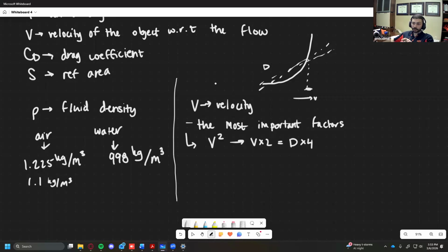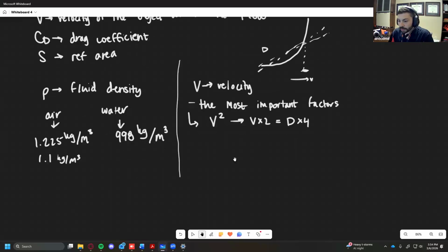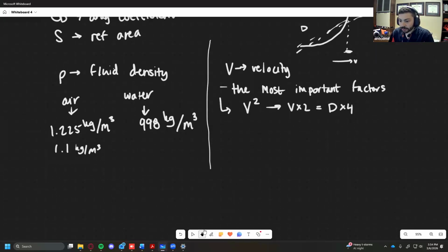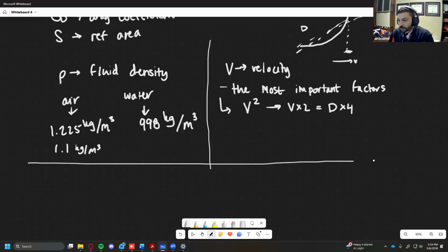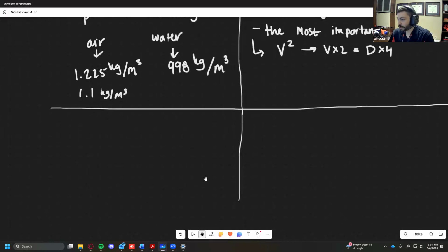This is why, let's file all the way back full circle, weight does not necessarily influence the glide time, but it does induce the speed. You can overcome some of your glide issues by going faster, but you have to be very streamlined, right? So you have to do a better job as a designer making your drag less so that you can fly faster. That's one of the tricky parts here. That's one of the reasons why aerodynamic drag increases dramatically once you get to these higher speeds. So the faster your glider goes, the more streamlined you need to make your vehicle. So you have to be very careful with that.